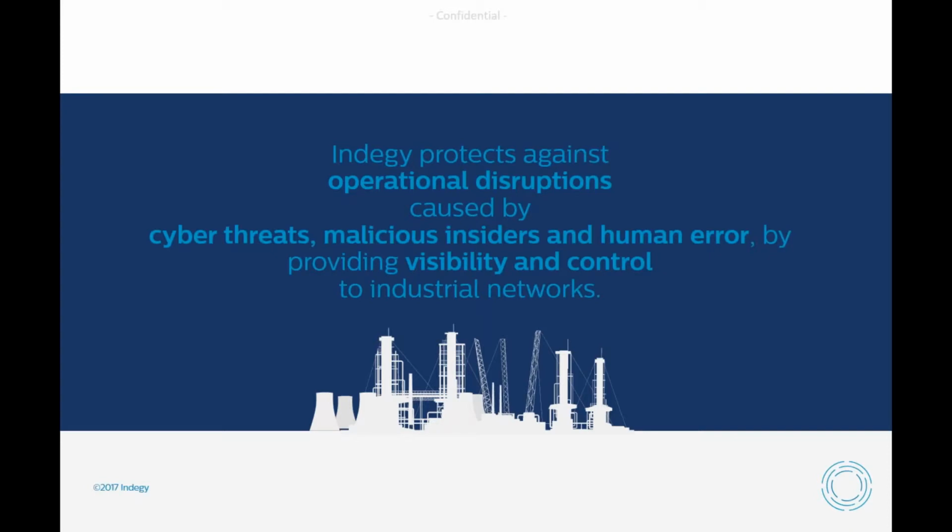And if we look at what Sid was talking about, in particular the cybersecurity maturity model from the ARC, and relate that down into a process that we can work through to implement that, the first thing we need to know about the industrial environment, as Sid highlighted, is you need to know what's there. So asset inventory is a very important part of starting this entire process. Next, once you know it's there, you need to monitor who accesses that stuff and how these things change. Also, where are they coming from, and the sources of these accesses and communications.